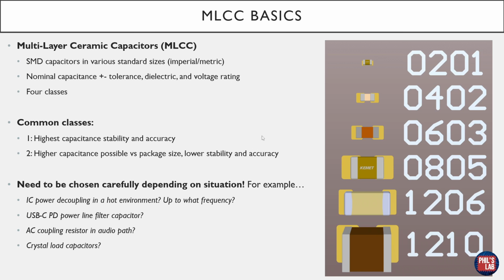If you're new to this, you probably will have just chosen your capacitors based on their nominal capacitance, so you might have chosen a 1 microfarad capacitor with some sort of tolerance, plus minus 10%, plus minus 20%. You might also have considered the voltage rating, such as 16 volts, 10 volts, 25 volts, and so on, but many people might not have considered the actual dielectric and disregarded that completely. But I'd like to talk more about this in this video.